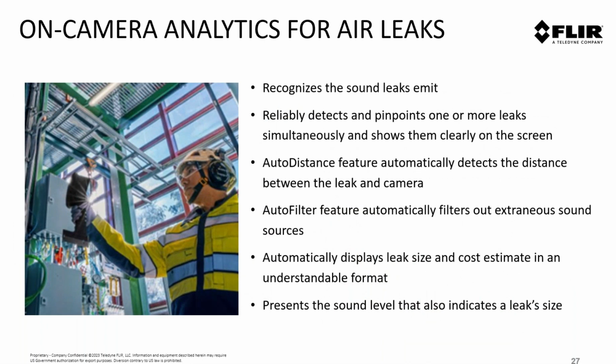What we're doing here is just recognizing that the sound leaks emit, to be able to detect and pinpoint one or more on screen. So that's another benefit of the tool. We have a single mode or a multi-point mode. The single mode will find the biggest leak on the screen as you're doing your scans. Multi-mode will find multiple leaks at the same time on the screen.